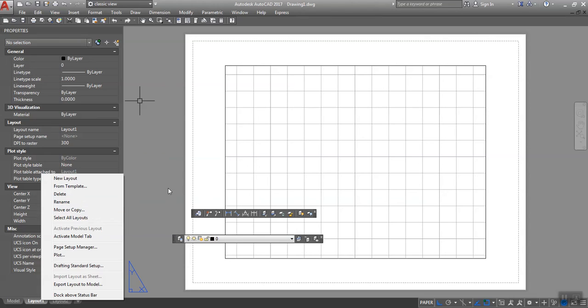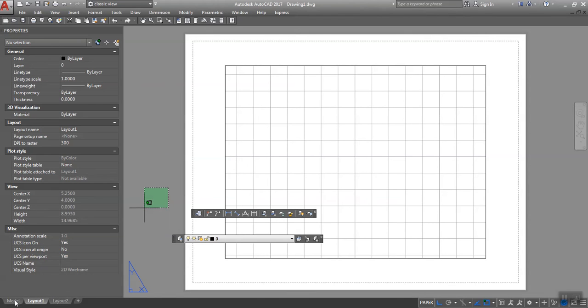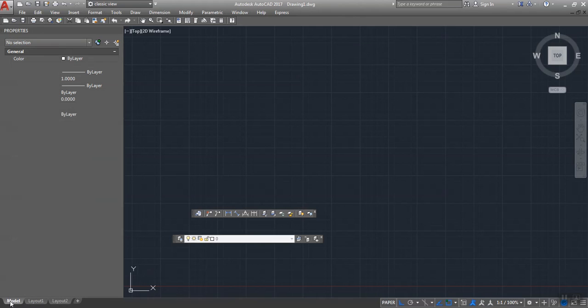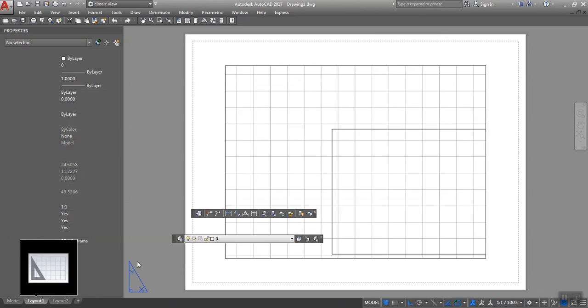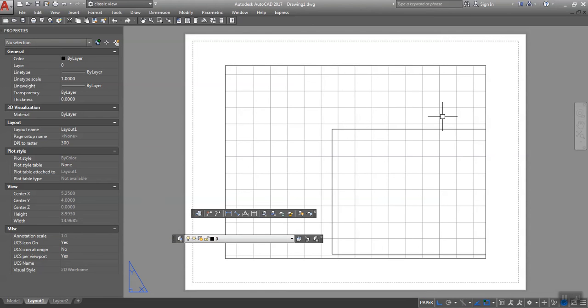And I will briefly show you, as you go to model space tab, you have to deselect the option that you were on, which I just did with clicking escape. If you click on model space, we'll do a rectangle, just any type of rectangle here. So there's your rectangle. If we go to paper space, here is your rectangle.